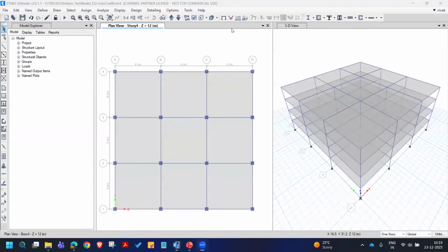Now, in the load combinations, the factor is 1.5, the partial safety factor for the earthquake. Now we have the omega factor coming in, and the base shear will increase with that. Yeah, the plugin does not add the basic 1.5 times dead load combination. That is, the user will have to add it.